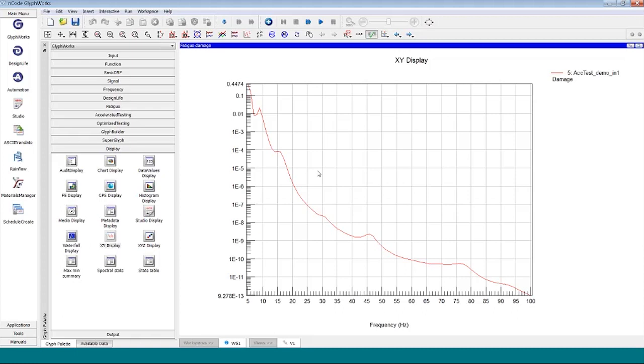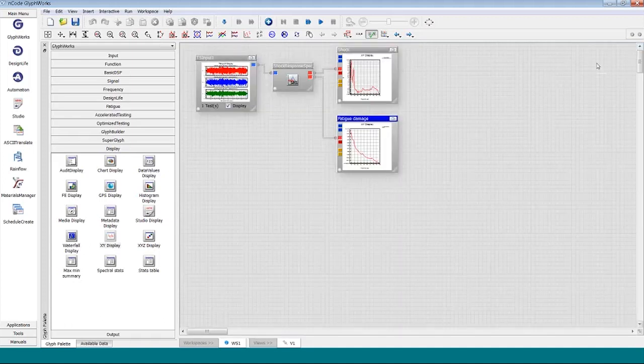We can understand the difference between one customer saying, we need this validated for 2,000 laps, and another customer saying, no, this is an extended duty cycle. Give me the shaker profile that represents not 2,000 laps, but 3,500. A different customer has a different demand for the design target. So that means the validation test needs to become more severe. All of this severity concept is shown quantifiably in this fatigue damage spectrum versus frequency.